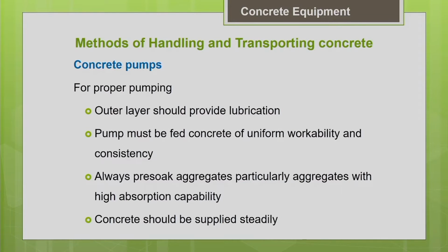So, what are the other guidelines? Let us see. As I told you, the important thing is that before pumping your actual batch of concrete, you have to do some lubrication. That lubrication will facilitate easy flow of your concrete through the pipeline. And we should feed the concrete pump with uniform consistency and uniform workability. That is very important so that you can have a uniform flow of concrete to the pipeline.